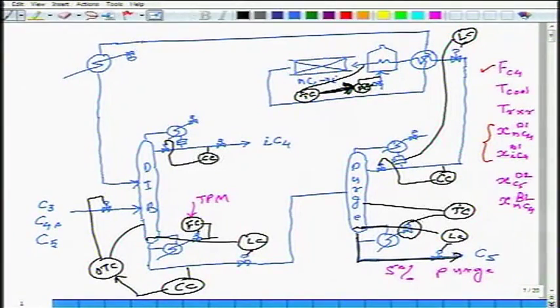But I am not willing to live with the back off that's going to come up here. If maximum furnace duty is X, I will be operating at 0.95 of X or maybe 0.9 of X, and that causes my throughput to be less by about 4-5%. That is something that's not acceptable to me. Do you see what I am saying? Which is why we did what we did.